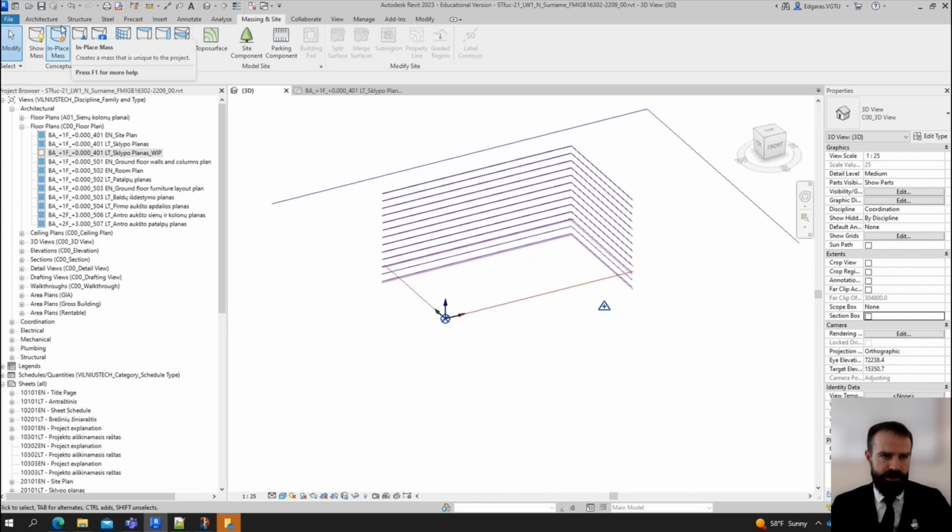So today I will speak more about massing tools, how to use massing tools to represent your building. And later from the massing tools, we can convert the building into roof, floors, walls, and curtain systems. My task is to show each tool, what you can do with these tools and how you can implement it into your design.